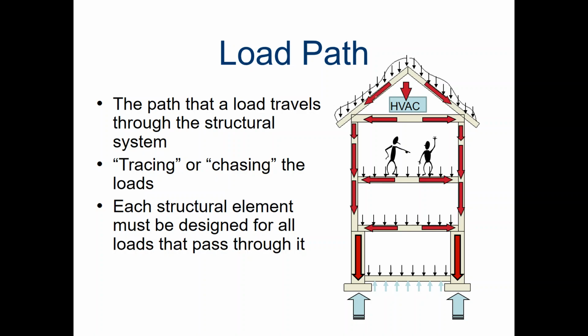So those first two, this arrow is representing that those loads are kind of held up at this corner here. And this corner is in turn held up by this column right here. But that column also is holding up, assuming that things are evenly distributed on this floor here, roughly half of this floor. The load is chased, the load path is heading over to this column here. So this column right here is holding up all of this stuff up here.